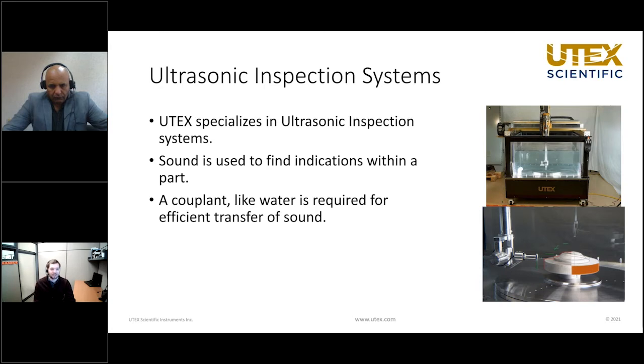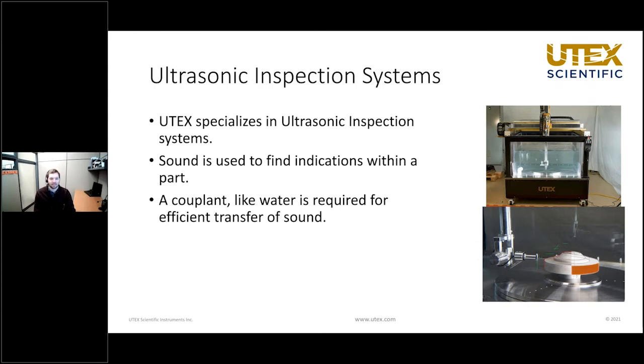To give a quick idea as to why our systems look like they do, it's important to have an understanding of how the technique works. It is the same basic principle as an ultrasound for a human, but it's for materials and is performed quite differently. When sound waves hit a boundary, the sound will bounce off and change direction. Some energy may reflect back to the sound source, in our case a probe, and some will scatter. In this picture here, you can see our probe, which both transmits and receives the ultrasonic sound waves.